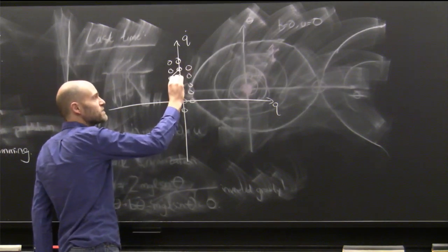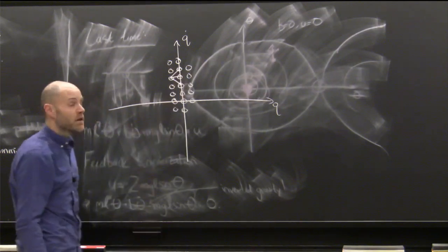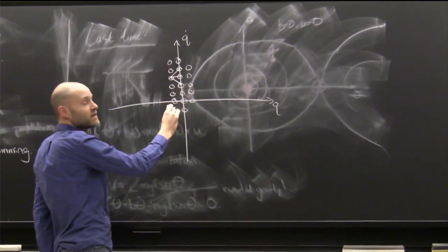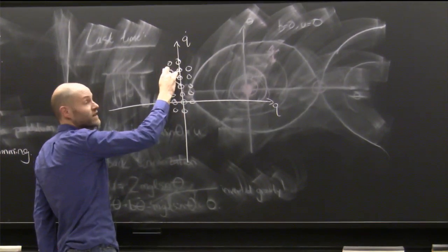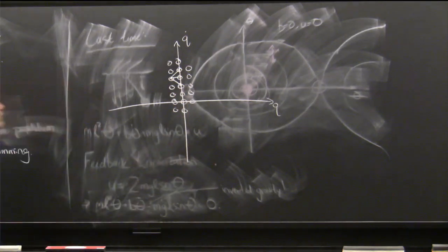But roughly speaking, you could say if I land close to that node, I'm going to draw a line to that node. But for instance, there are no edges up and down here. Up here, for instance, does not connect to here. It certainly doesn't connect to this guy over here, right? And then the minimum time problem for the double integrator just becomes a shortest path problem on this graph, approximately.